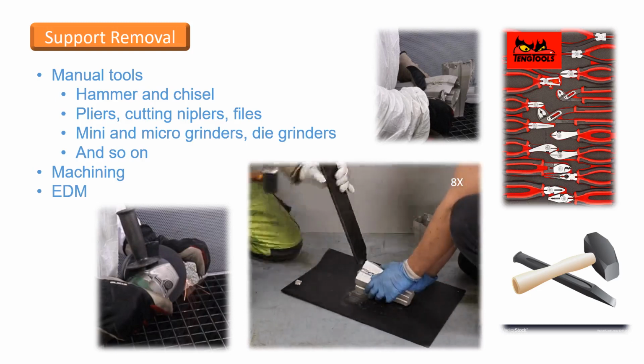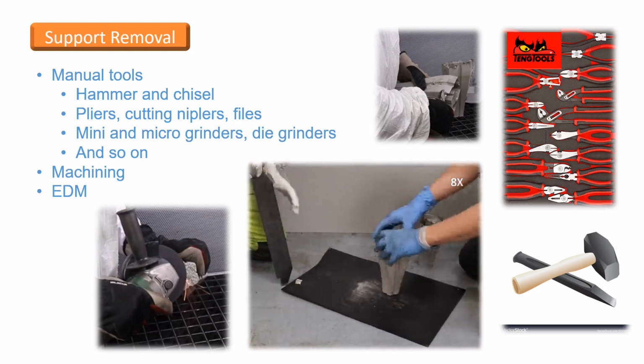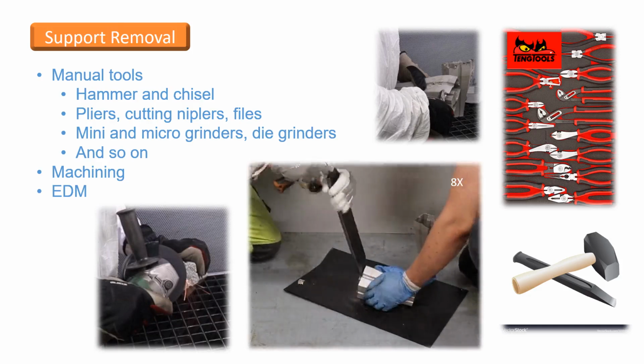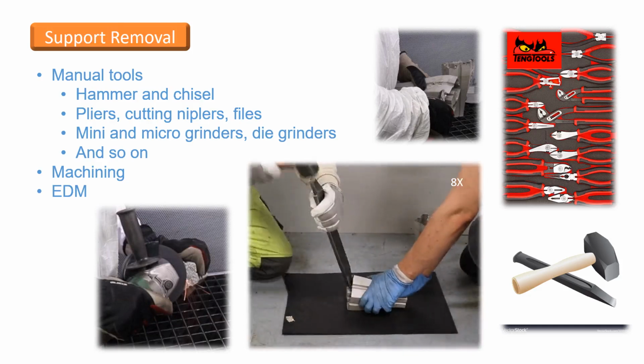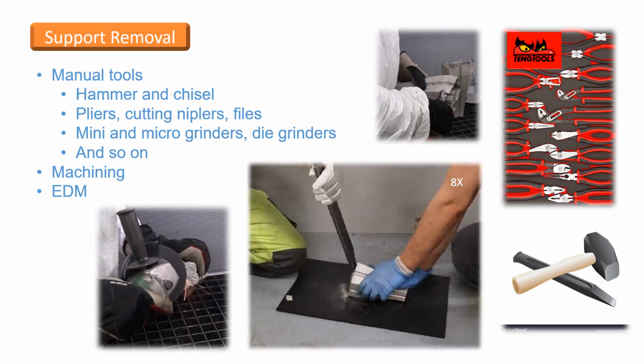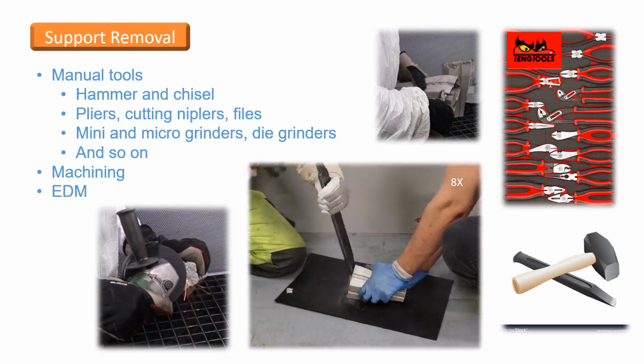Generally, manual removal of supports is considered laborious, but when supports are designed to be easily removed, it is understood that manual removal may still be the fastest method of removing supports. If the parts contain precise geometrical features that are easiest to make by machining, it is advisable to design the supporting structures so that they can also be removed by machining at the same time.